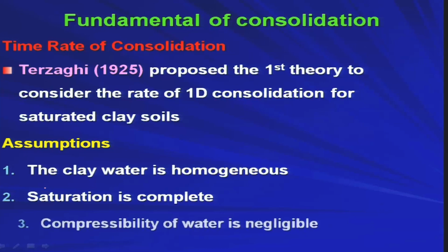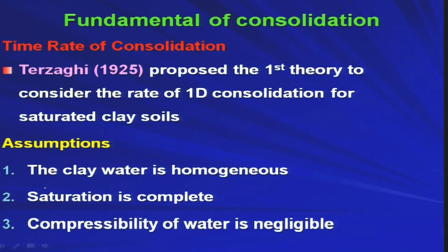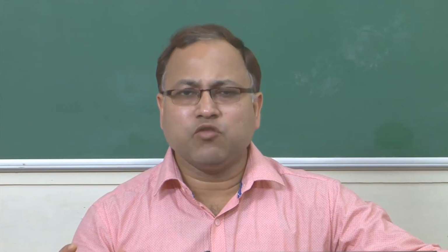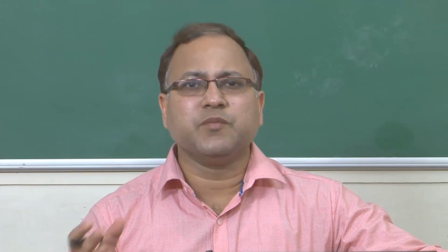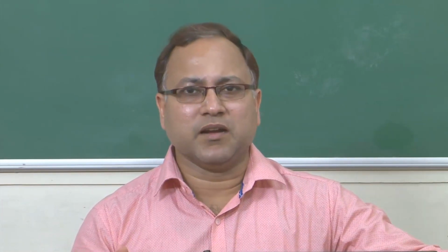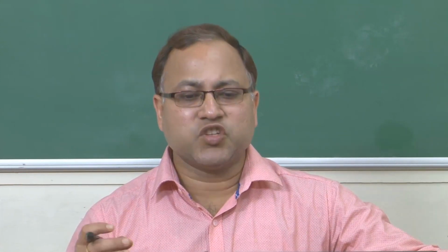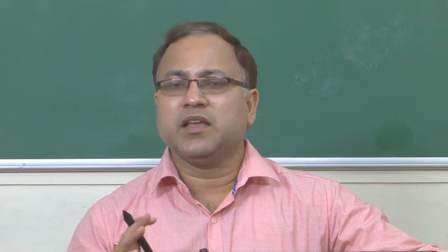Then, compressibility of water is negligible. That means water is considered a completely incompressible material, and that is a good assumption. There is no problem in that. We know from mechanics that water is an incompressible material, and therefore, if we neglect the compressibility of water in the consolidation theory, there will be no harm.